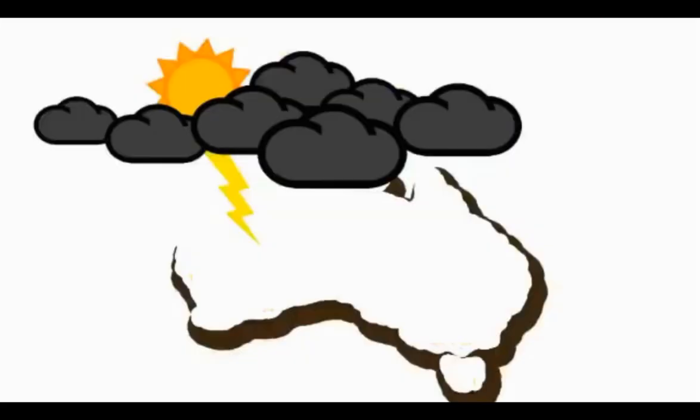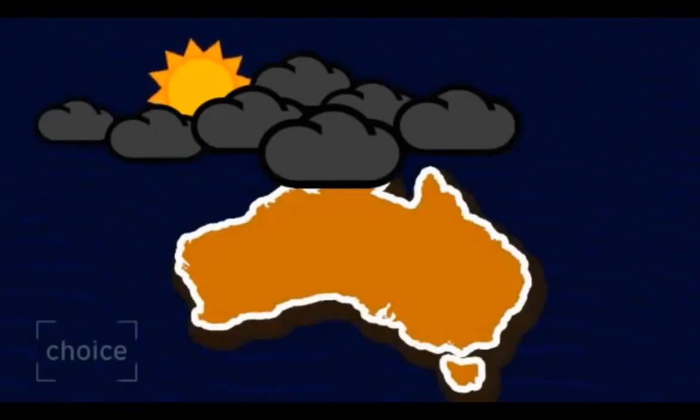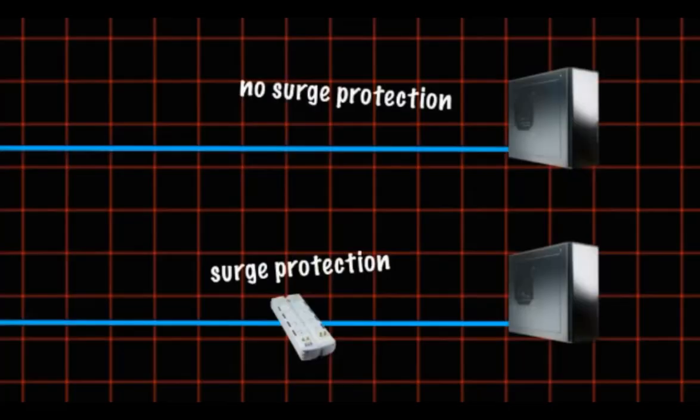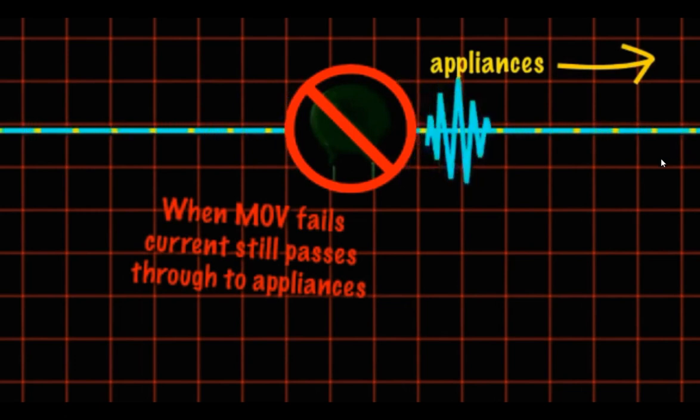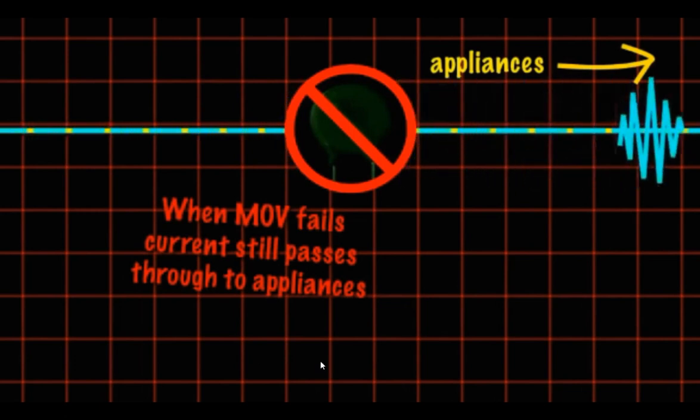Now let's understand it with a video demonstration. Here you see there is a lightning strike onto or near to a power line or distribution line, which creates a high kiloamp surge in the line, resulting in high kiloamp surges beginning to travel along power lines to our end devices. See, there are two cases: one has a surge protection device, and if any surge comes, it will suppress it, while in the other case, there is no surge protection device installed, and any high kiloamp surge will be able to destroy the device. If your SPD is burned out by a high kiloamp surge, then you have to replace it as soon as possible, because a burned SPD cannot suppress the surges, leading to the failure of equipment.